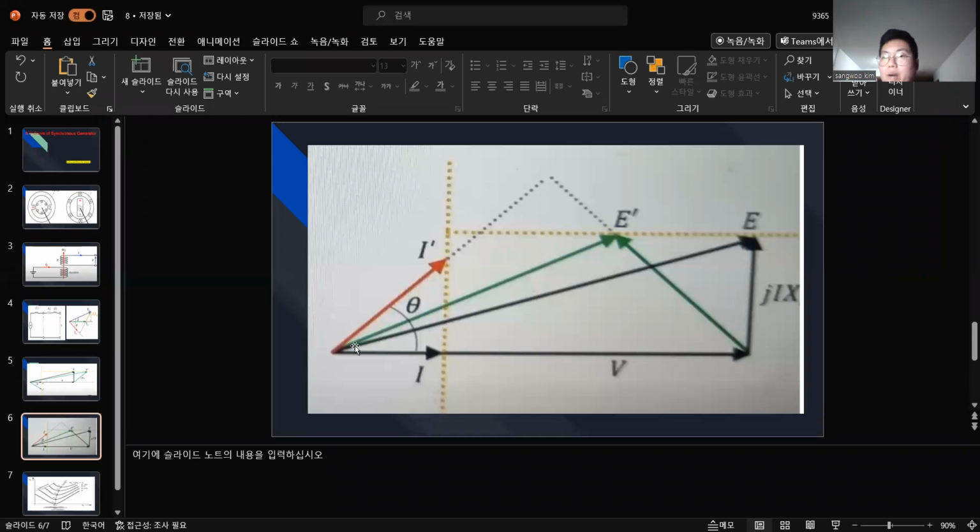So this is the under excitation part. First of all, the first part is when your power factor is 1, here, this part, the black part. The equation is E equals V plus jIX, right? We want to decrease IF. What happened? Let's see. We now expect that E is decreased, right?